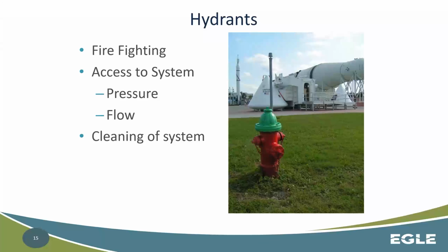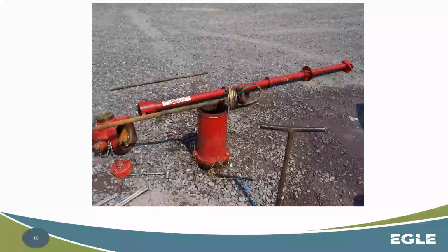Hydrants are one of the most important access points to a distribution system. Yes, they are out there with the primary function of fighting fires, but they give us access to an underground system that we can otherwise not really tap or do anything with. So hydrants become a very important part of distribution maintenance and operation. In this scenario, this was a system that got called out because their firefighting folk were using the hydrant, and after they were done using the hydrant, they closed it off.